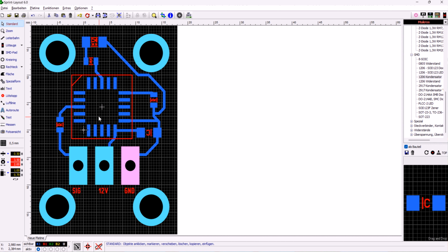And also sometimes between pins, when you have RF circuits, etc., they are mostly shielded with ground planes on both sides, so they are not influenced by other parts of your circuitry, but also from outside sources. So shielding is one reason, and the other reason for using ground planes is, of course, saving traces.